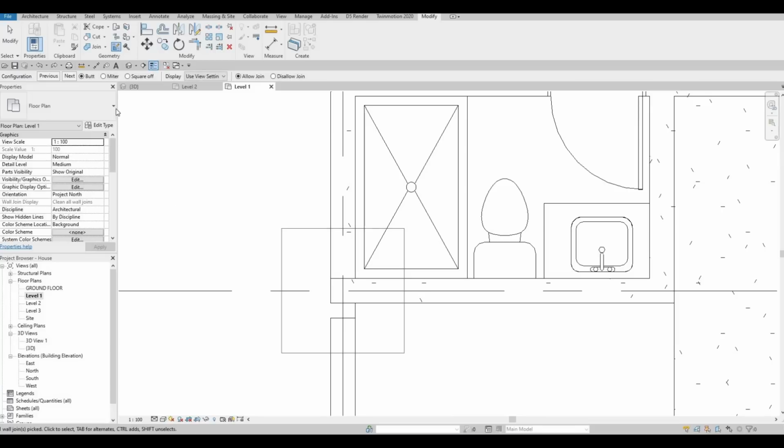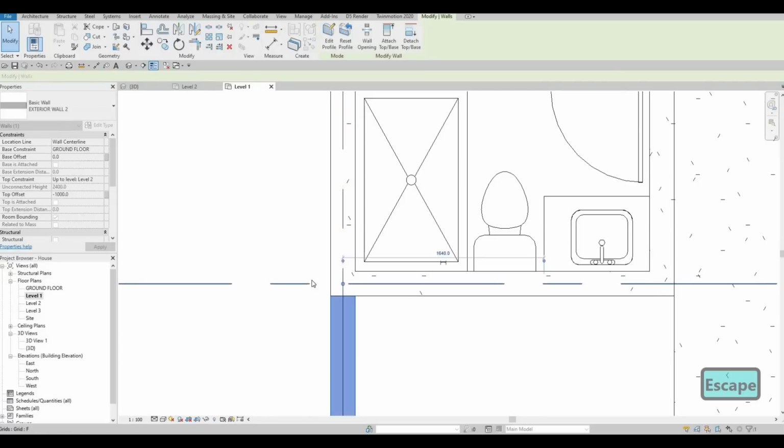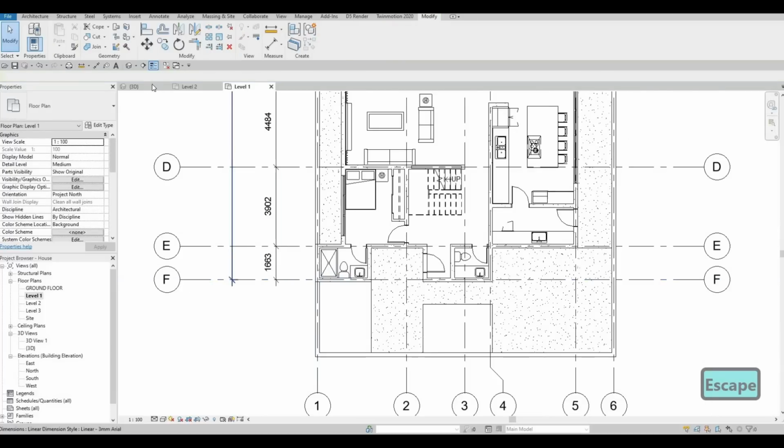So I'm gonna select this connection, and we want it to be squared off. Now it's giving you some options. Once we click next, it will do what you wanted. So I want it to be full, and this one is the butting joint. Once we do that, we need to just move this so that everything is connected.